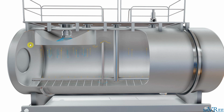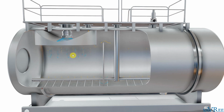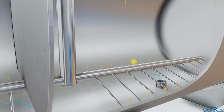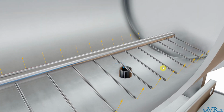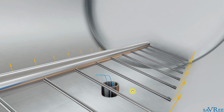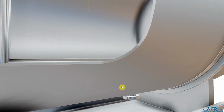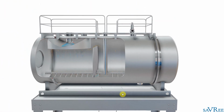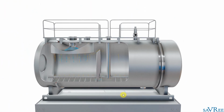As I say, this is now our boiler feedwater tank, and we're going to draw out boiler feedwater through this pipe in the bottom of the tank. That's represented over here. Once we draw out the boiler feedwater, we can send it to a booster pump or series of booster pumps. Maybe we'll also pass it through another heater, a high pressure heater, and it will go then to our boiler feedwater pumps, which are multi-stage centrifugal pumps.